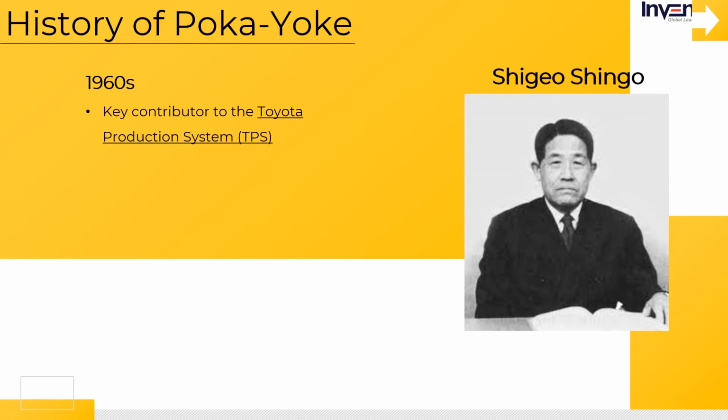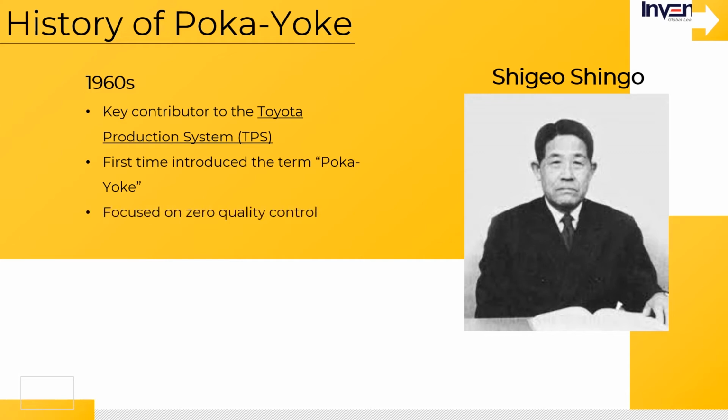Then, he redesigned the process to be completed in 2 steps. The first step was to place the required springs in a placeholder. Second, they must insert the springs into the switch. As a result, if a spring remained in the placeholder, it would be clear to the worker that they had forgotten to place it in the switch. Then, they could correct their mistake immediately.